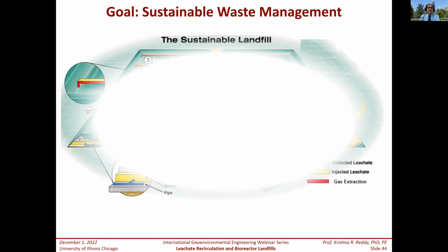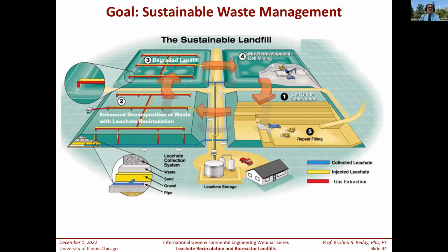So the whole idea of bioreactor landfills can lead to a sustainable waste management approach. So let's say you have a cell, and you put the waste in there, and then you degrade it, and then once degraded, you can mine it, and then open up the space again, put the waste. So the idea is, these days it's hard to find landfill space, right? So this one is not like dump it and cover it and walk away and have no use of that land, right?